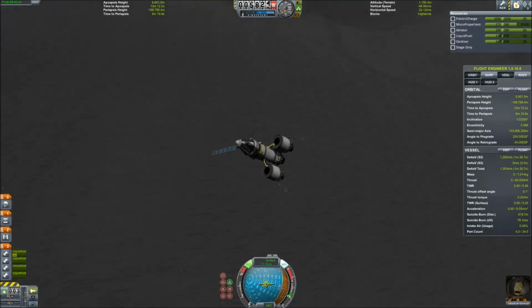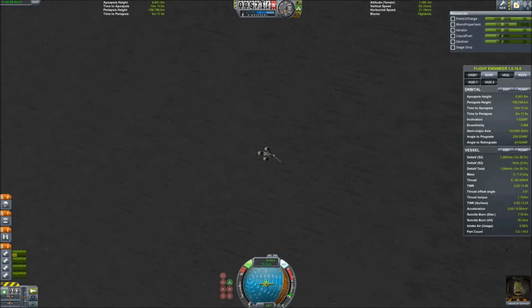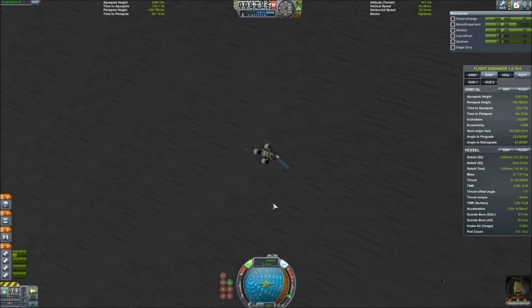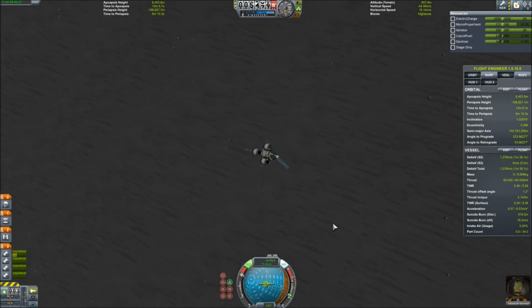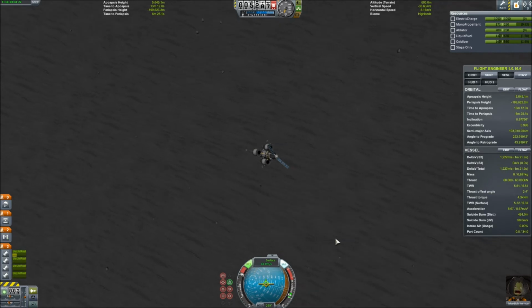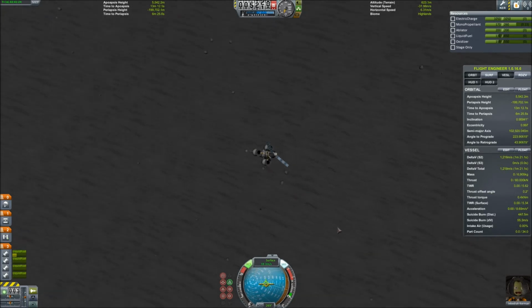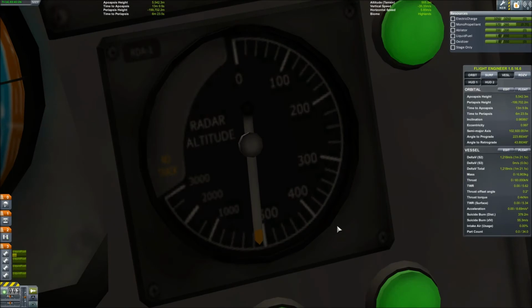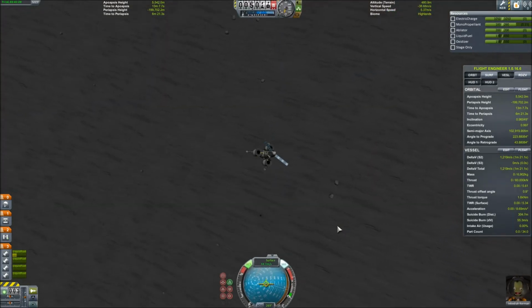Now you see I also looked up and checked exactly where the sun was with respect to my aircraft and the surface of the moon. That was to tell where my shadow would be. So then I looked down, having determined exactly where that shadow was likely to be, and I watched until it appeared. This gives me a very good representation of exactly when I'll make contact and be able to land.